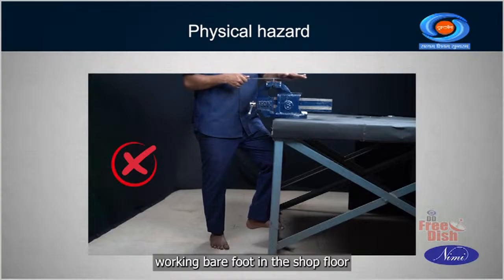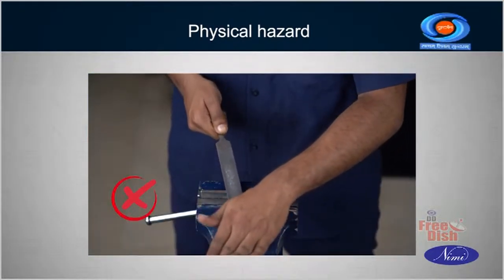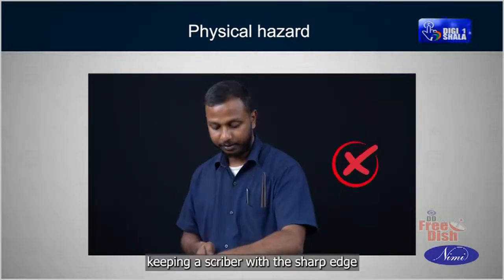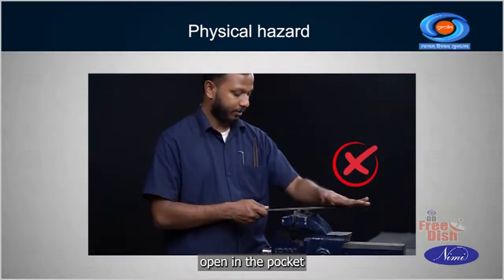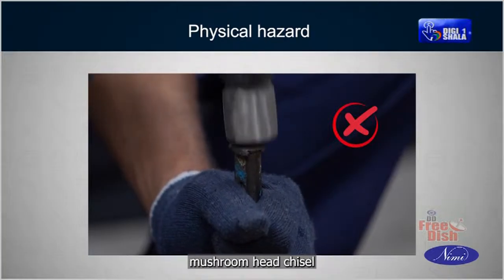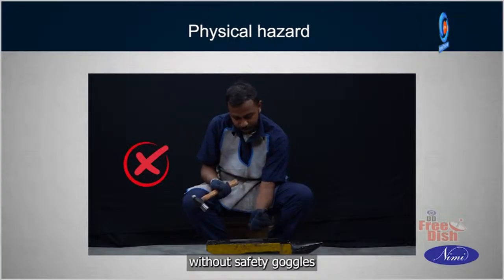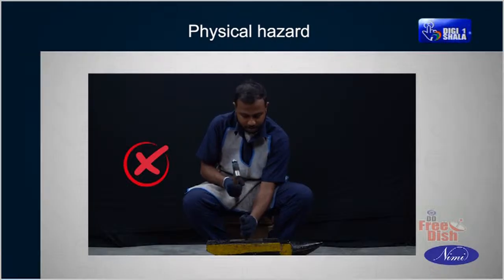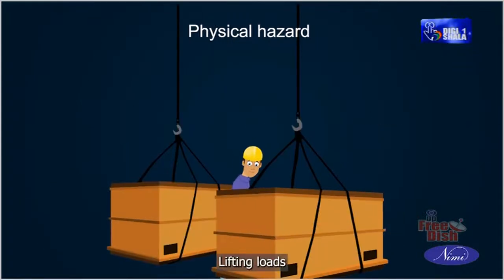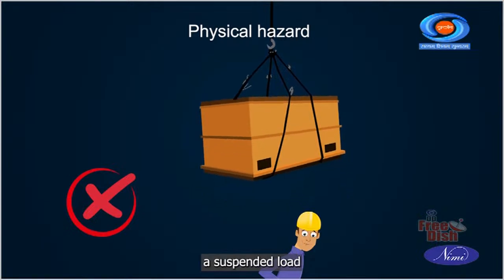working barefoot in the shop floor, using a file without a handle, striking on a chisel head with a ball peen hammer without wedge, keeping a scriber with the sharp edge open in the pocket, chipping a metal surface with mushroom head chisel, chipping on a metal surface without safety goggles, lifting a heavy load with damaged slings, lifting loads while people are working nearby, standing below a suspended load.